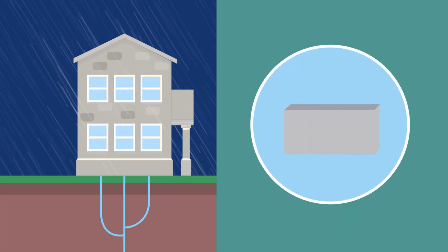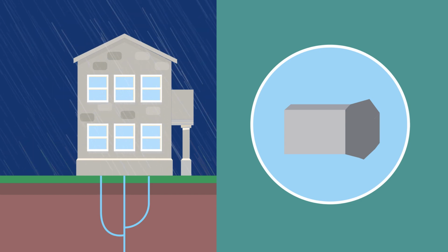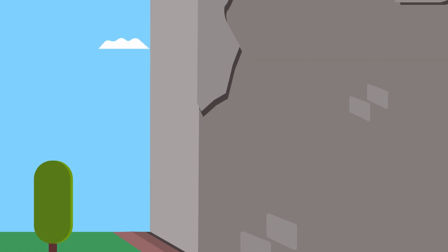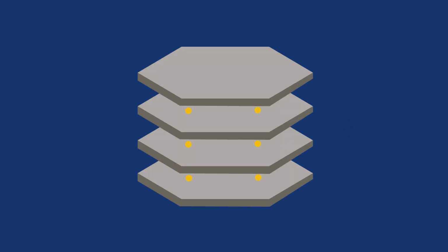For stones that are initially dry, the wetting from their exterior surface can lead to warping and buckling, which probably contributes to the contour scaling observed on such stones parallel to their exposed surface. In both cases, the use of swelling inhibitors for clays can reduce the dimensional changes and therefore also the expected risk of damage.